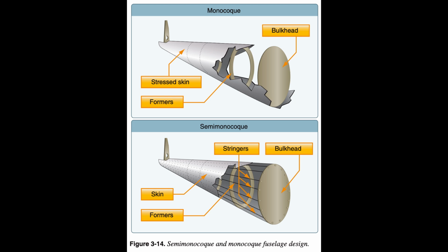Figure 3.14. Monocoque. Monocoque construction uses stressed skin to support almost all loads, much like an aluminum beverage can. Although very strong, monocoque construction is not highly tolerant to deformation of the surface.